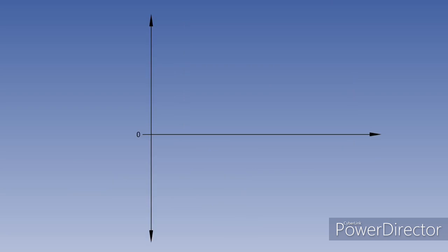We will now take what we have learned about longitudinal static stability and, using simple sketch graphs, consider some of the variables. Here are the two axes. The vertical axis represents pitching moment, with increasing nose-up pitching moment above the horizontal axis and increasing nose-down pitching moment below. The horizontal axis represents lift coefficient, increasing to the right.